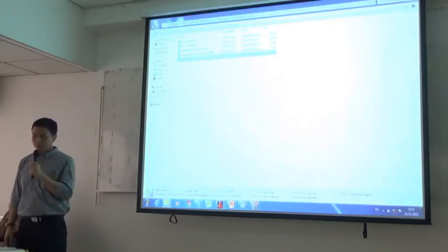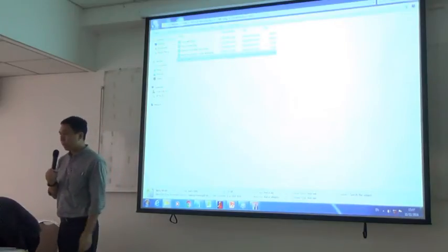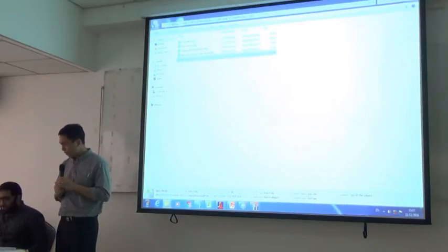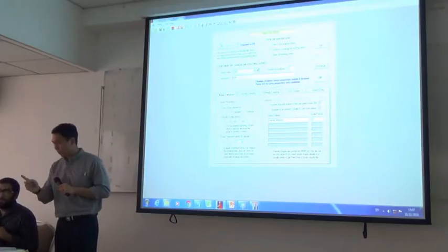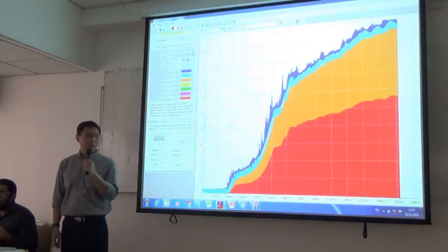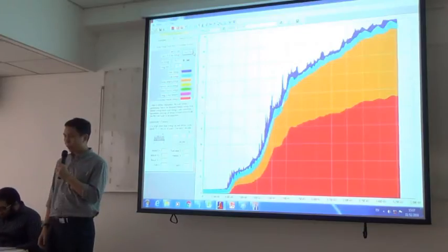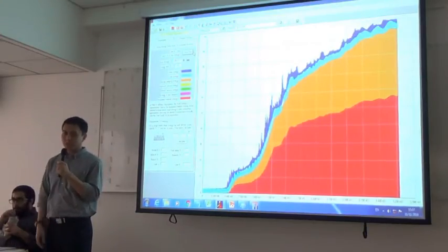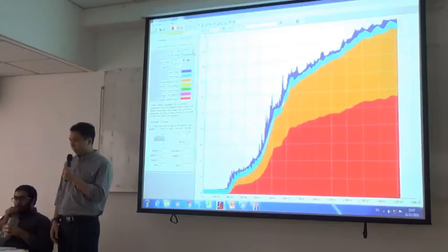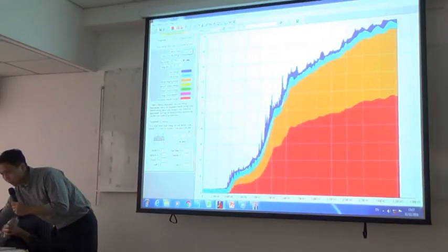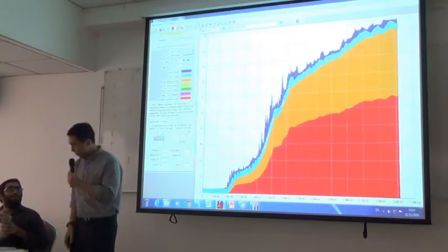So we will continue the overall response analysis results from our nonlinear analysis. First, after we conduct the nonlinear analysis, we have to check the energy error from our results. All the analyzed models are in your computers. You just open it and they are already analyzed. And please go to the analysis phase and click the energy balance button.